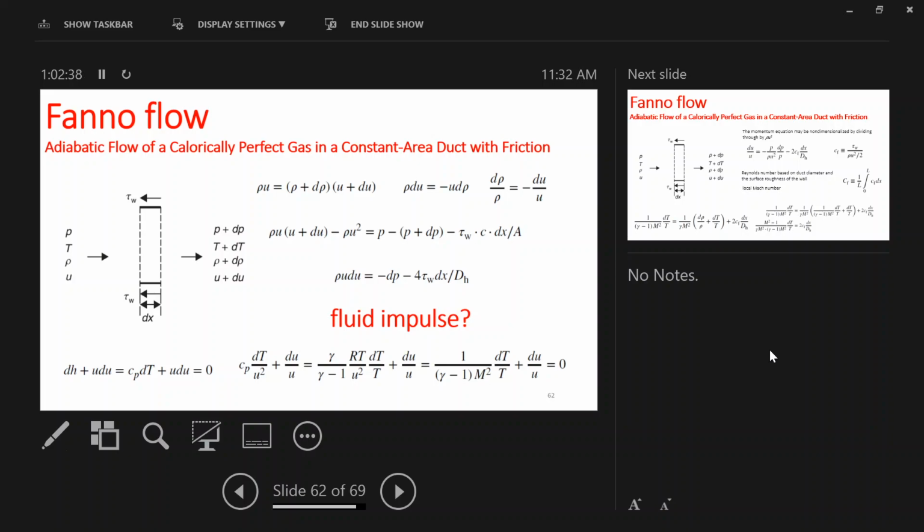Okay, so if you were dealing with a rectangular duct, the hydraulic diameter would be 4 multiplied by, let's say, a square duct, 4 multiplied by length times width over the perimeter, if it's a square, yeah, 4, right? That's right. Okay.